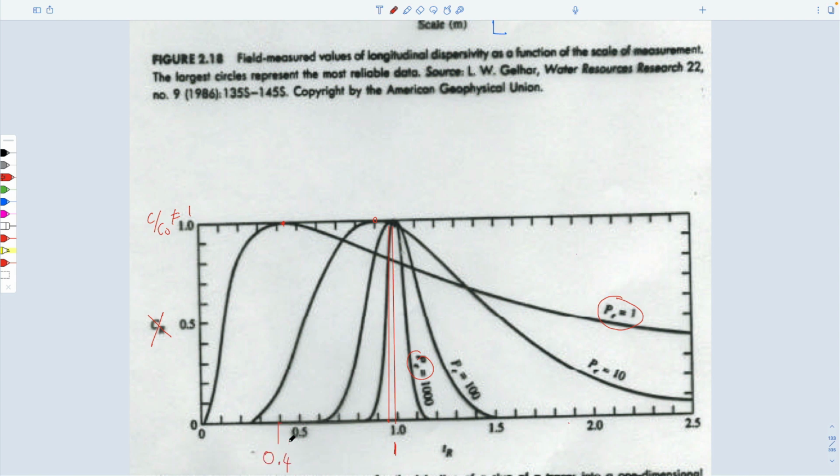It's a pore volume of 0.4. And so this suggests that it kind of arrives earlier because of diffusion, but this is a wonky reference frame, because actually there is no residence time distribution, because this is mainly being driven by diffusion in the aquifer. So this is the corresponding curve that we had for the residence time distribution from before,